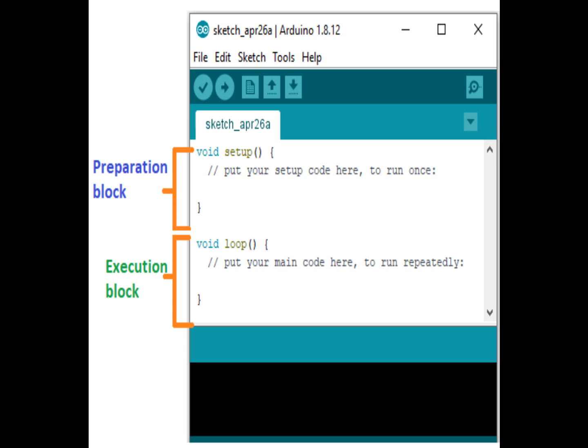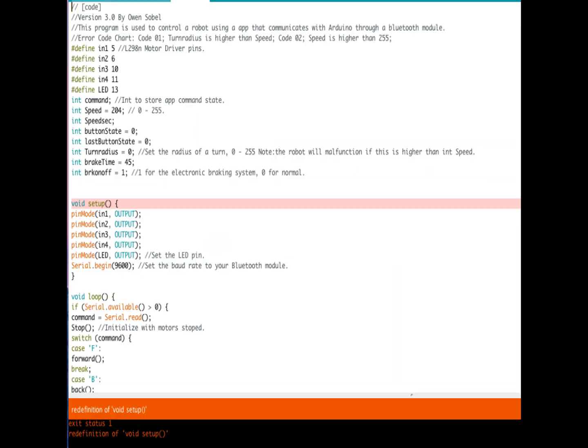The main functionality though occurs in the loop segment. Like the setup line before it, this is another required Arduino sketch function. While the setup function sets your Arduino up, the loop function, well, it just loops. This is where the bulk of your Arduino sketch is located. The program starts directly after the opening curly bracket and runs until it sees the closing curly bracket, jumps back into the first line of the loop and starts all over repeatedly until you disconnect the wire. The loop function will run over and over until the Arduino is reset.